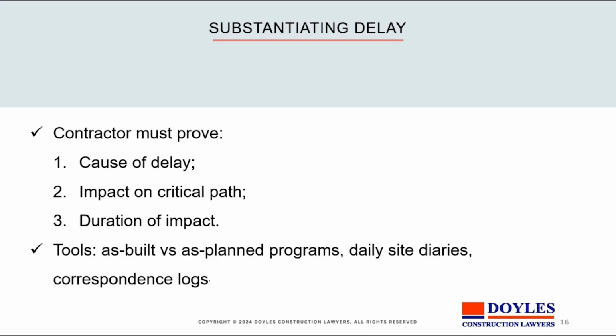Additionally, you can get consequential disruption in the sense that it may not have been able to get to the correct spot, and therefore its listing of the materials is out of whack and required more handling once it was loaded. So it's again a matter of writing up and keeping a good site diary to connect these things together and make sure that you're able to be properly rewarded for a delay not your fault.